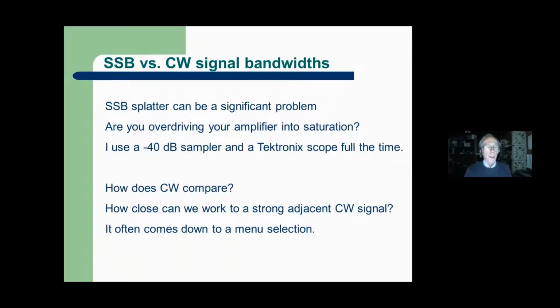As you saw with that pure signal example and the guy who was wide, I'm guessing he was overdriving his linear. I use a sampler on the output of my amplifiers and feed a scope. And so I know I'm not clipping.